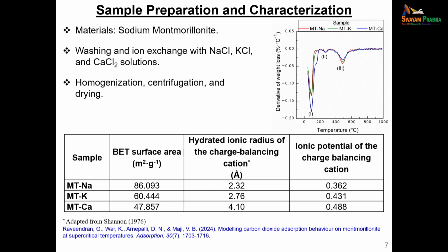Then if you look at it, the first peak represents the free water, bound water, leaving the clay material when you heat it in the range of 180 to 200 degrees. If you cross further, strongly bound water will go. If you do it further, the clay itself will decompose beyond a certain point. So we don't want to destruct the structure of the clay.